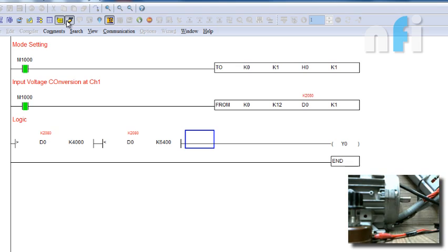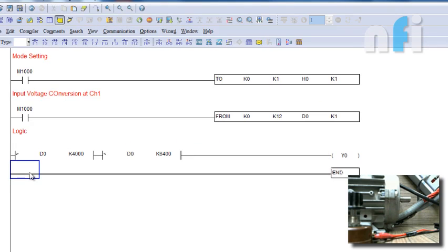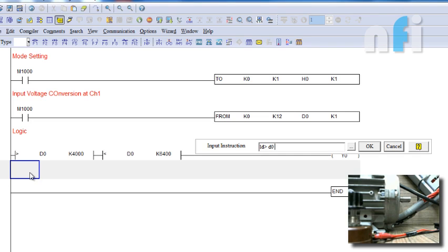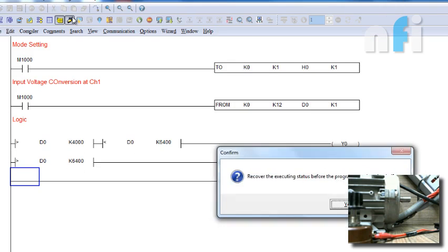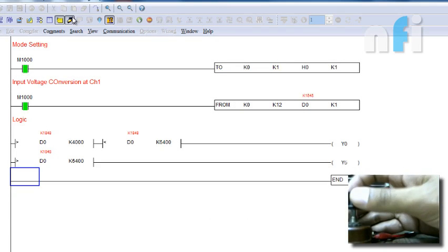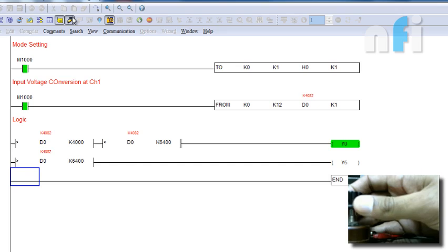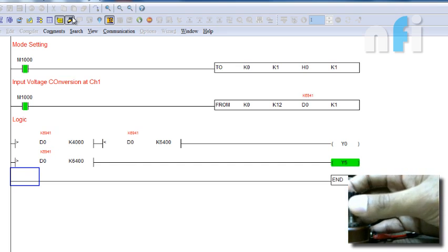You can play with these digital bits. By play, I mean you can manipulate the signals in whatever way you want. You can also have some alarm signal. If your voltage reaches above 8 volts, you can have an alarm here. So above 8 volts, I can have some output here. I can turn on an output, with which I can connect my alarm, which will give me an alarming situation. So above 6400, the motor is off, but the output is on. With that output, I can actuate anything. That is up to us.